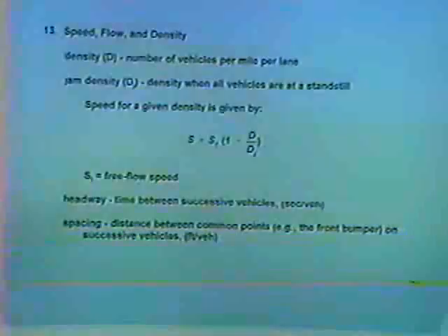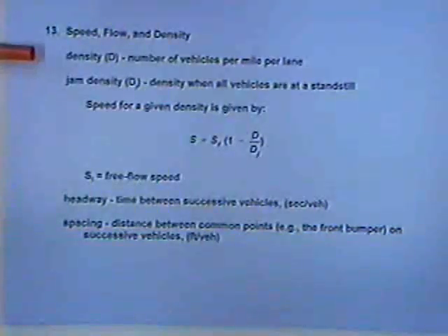And the curve that we looked at a few minutes ago, where we were looking at level of service, it had those 3 parameters in it. It was volume by speed by volume, but then we had superimposed on it the density values as well. And let me just talk about density. Usually it is defined as the number of vehicles per mile per lane.